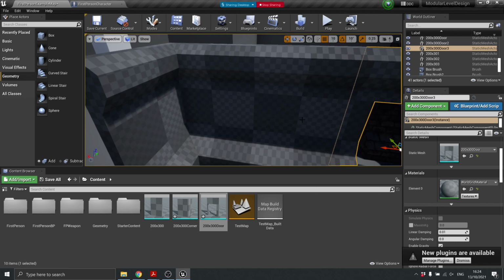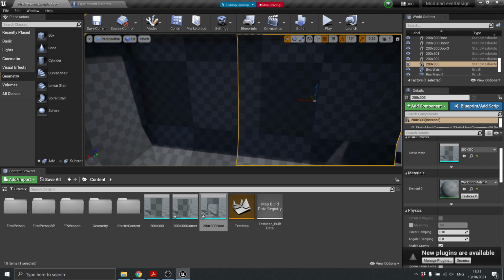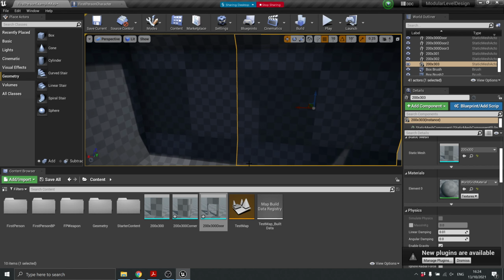The one thing that I'm going to show you there is if I drag this, we were talking about texture clipping there where the corners met. This is easier to see on my screen than it is here, so I'll try and zoom out of it. What's happened there is we have two identical surfaces in the exact same place with materials overlapping one another and they're basically fighting.